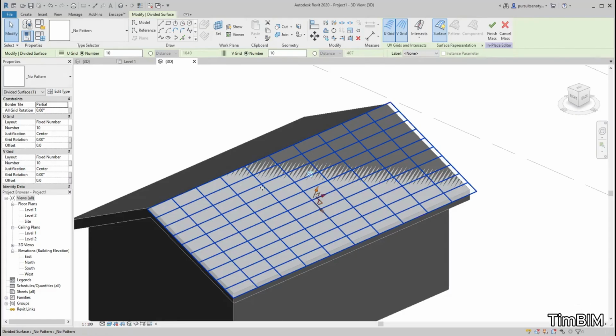So we'll go ahead and divide this surface to give us a cell of 300 by 300. You select these lines. It's already highlighted. Then you come here. They are asking you for the number, which you use if you know the number of rows or columns that you place before you cover the surface. But in this case, I don't know the number of tiles that I'll place or the number of rows my tiles will cover. So I'll use distance mode.